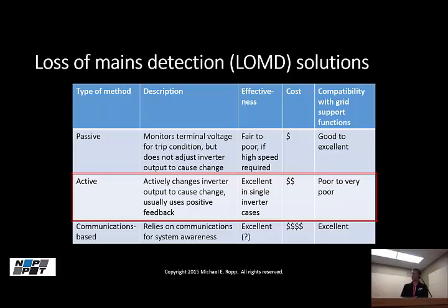What if that recloser were, say, a pole top recloser, and I needed to get direct transfer trip to it because there was a risk of islanding downstream? It's logistically very difficult to do DTT on a pole top recloser. They're generally not equipped for it. There's no COM port or anything. They're outside the secure perimeter of the substation, so there are NERC-FERC issues that come into play. So it can be kind of a tricky thing to do.